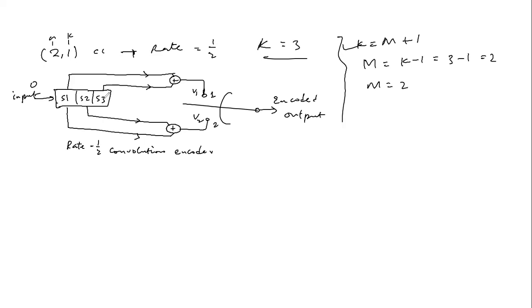The fact that the 2 final stages of the shift registers are able to hold past inputs, because what was here before is now held by this, and what was here before is now held by this, means they may be regarded as determining the machine's memory. And mind you, here they have 2 memory, because they're able to hold on to 2 past inputs whenever a new input is fed into the first shift register. So if we feed in a 1 here, whatsoever moves here, moves here.